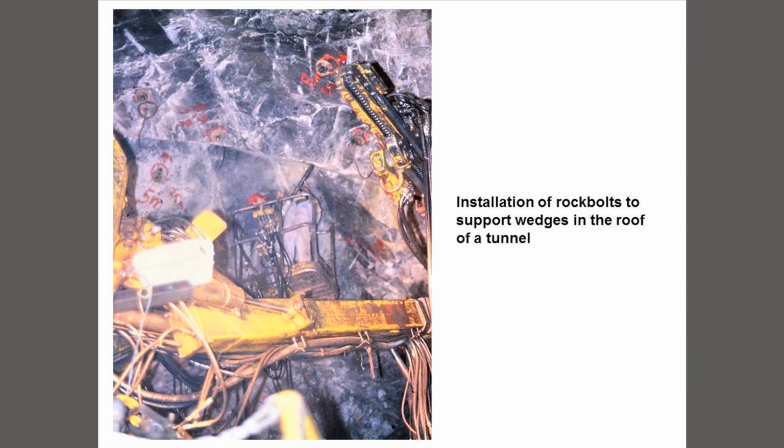This is a photograph which might be a little bit difficult for you to interpret, but you can see a man in the middle of the photograph there drilling a hole for a rock bolt using what we call a jack leg, or a drill with a jack forcing it into the rock. And you don't need me to tell you that's a very dangerous operation. So you come to ask yourself, can I really put people under an 8 meter wide span, fully open, and ask them to do that job? The answer is no, you can't. And so how do we overcome that?